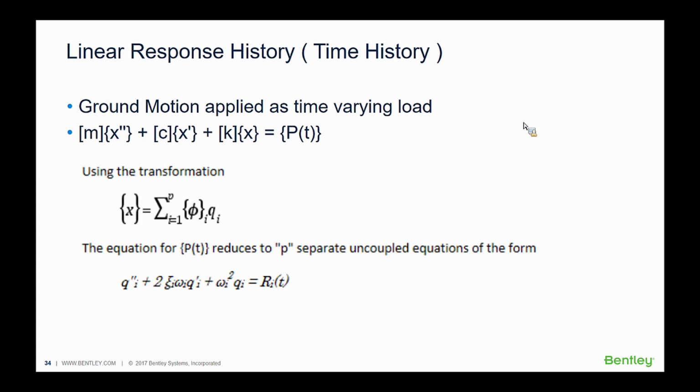The machine load is represented using a harmonic forcing function. And if it's a blast load, it's just entered as random force versus time data. When it comes to seismic analysis, though, the force due to earthquake can be represented as ground acceleration versus time pairs for the entire duration of the earthquake. Although I must say here that response spectrum is much more widely used compared to time history when it comes to applying seismic loading.